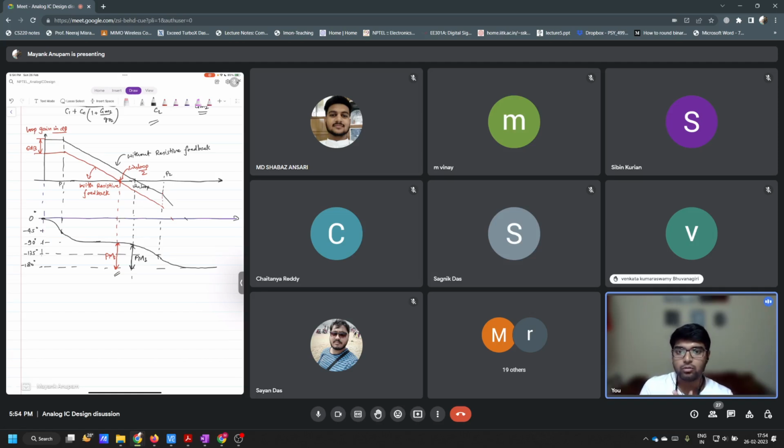You do not know what the consumer will be using it for. They can use it for unity gain configuration, or for high gain applications. So it is a difficult task to make it stable across all possible cases. So an engineer has to design it for the worst possible case where the op amp can become unstable.